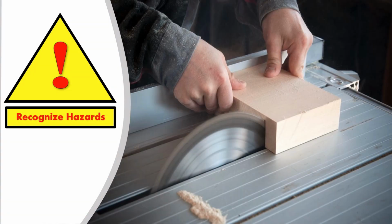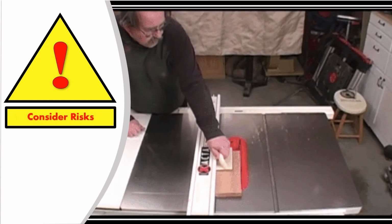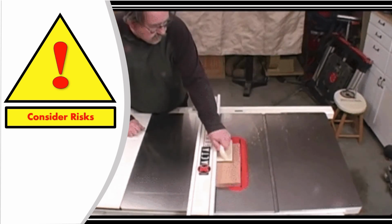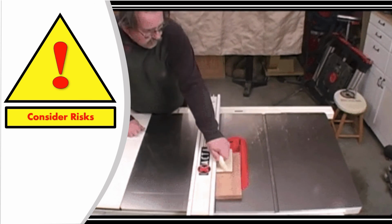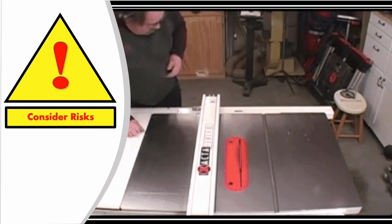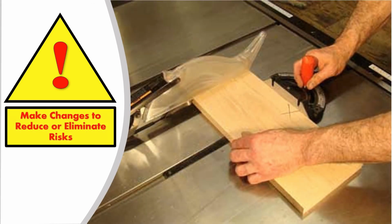We want to learn how to recognize hazards. Then you want to think about, with those hazards, what could happen. Consider the risk. So you make changes to reduce or eliminate those risks. See here, you got a miter gauge and you're using it to support the board.